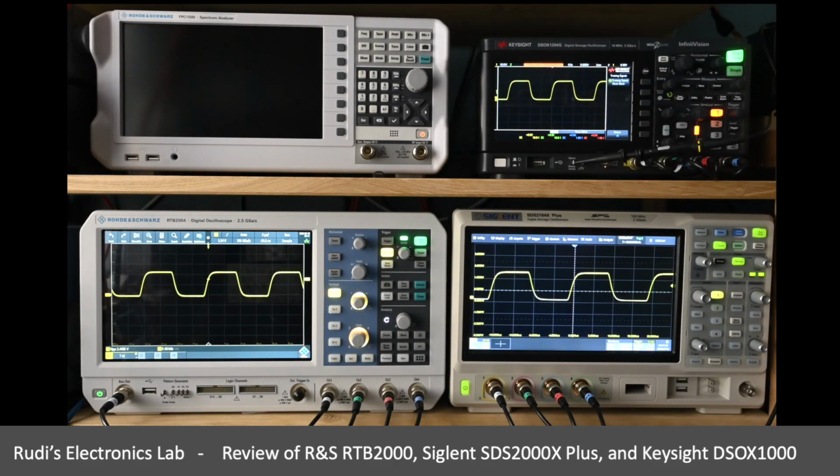So what are we looking at now? We're looking at the 50 kilohertz clock signal, but it has an infrequent glitch in there. Actually, there's one glitch per 50,000 clock cycles. So basically that's about 1 per second or so. By having this clock with this infrequent glitch signal here, we can test the ability of these devices to show issues with clock signals or otherwise in current behavior of a device under test.